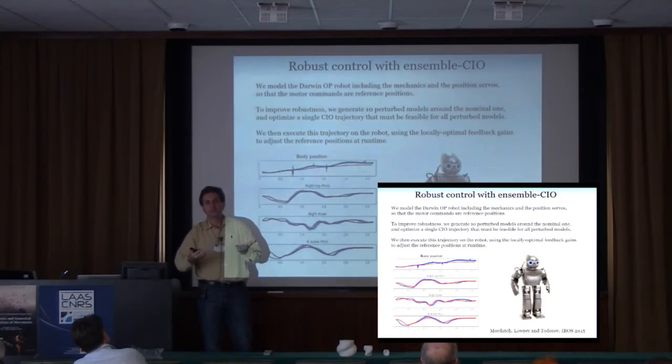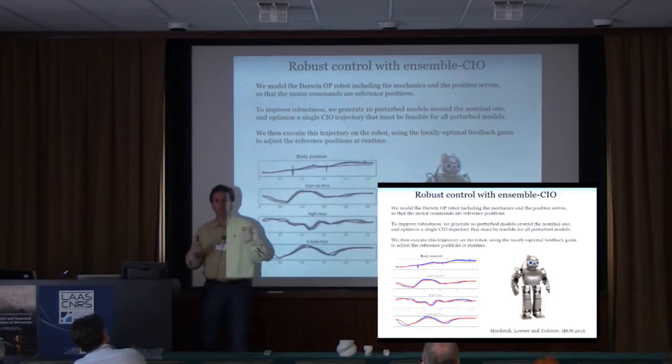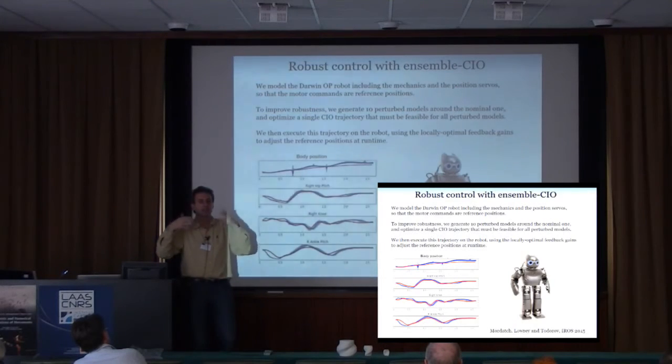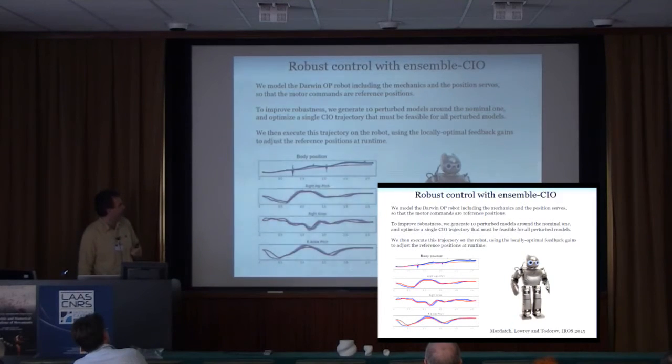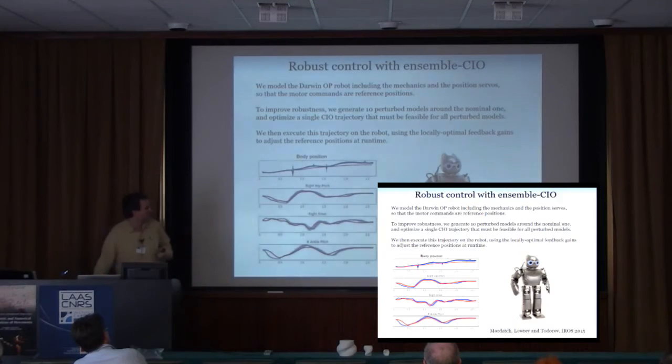And usually that's the case if you buy enough sensors. But in practice, the sensor noise could make it very difficult to disentangle some parameters. For example, damping and inertia are very hard to disentangle, because both of them cause the system to slow down, right? So you really have to inject crazy control sequences to tell the difference between them. And once you start doing that, your system starts shaking, and you're in a mode that you may not actually be modeling. So the reality can be pretty nasty. In other words, just because we can do it for this simple system doesn't automatically mean it's going to scale to a full humanoid. But next time I see you, I may be able to tell you that.